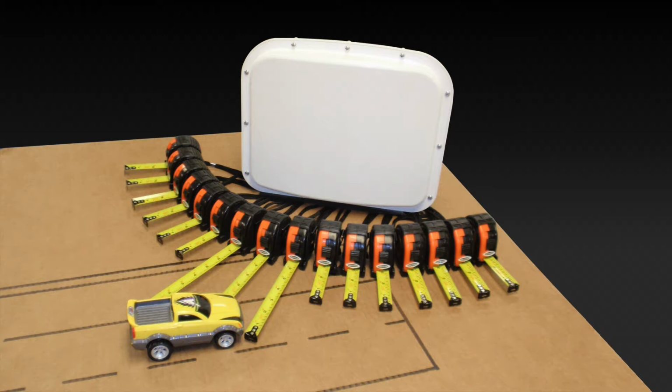And as the illustration shows, it works on the principle of having 16 different radar beams. Each of these beams is steered to a slightly different angle, and the combination of all these beams creates a 90-degree field of view. So each of these beams is used to measure the distance to the targets in front of the sensor.